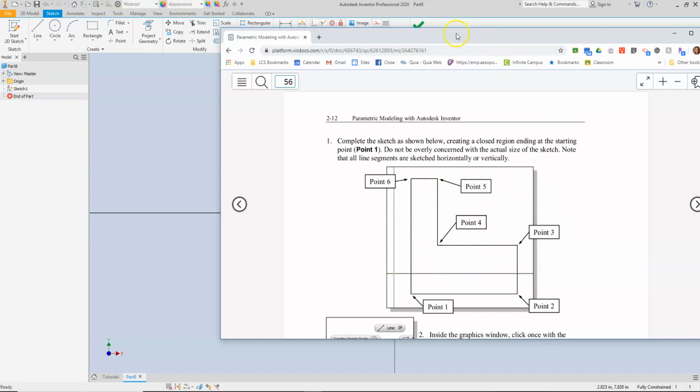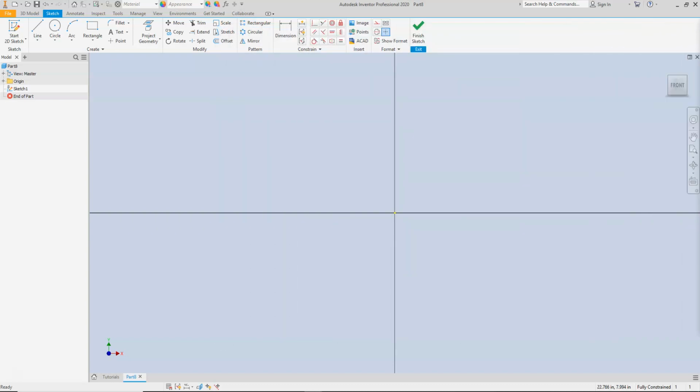we're doing this. As you start drawing, you'll see that your line command has the dynamic input that you're probably familiar with. This is built in. This is just to give you a heads up approach to entering the lengths of the lines. But as we're doing these problems, I want you to use a sketch method first. This is part of the parametric modeling. I want you to sketch the part, and then we're going to define the constraints afterwards.